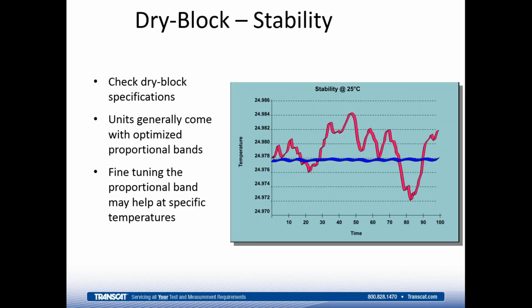We often call it drift, where maybe I'm looking at the difference of the reading over a period of 90 days or 6 months or a year. But in the short term, I'm going to be concerned about that stability, because my ability to provide a good calibration and be certain of the temperature value is going to depend greatly on that stability. Especially if I'm using an external reference thermometer, the stability becomes a pretty significant component in my uncertainties.